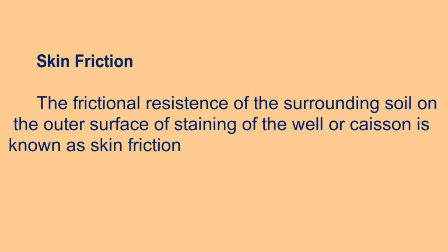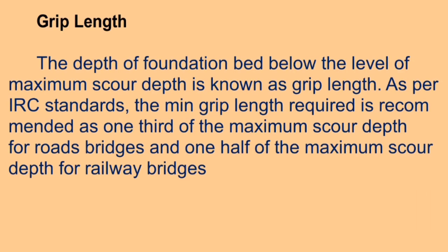Now, what is skin friction? The frictional resistance of the surrounding soil on the outer surface of the well or caisson is known as skin friction. What is grip length? The depth of foundation bed below the level of maximum scour depth is known as grip or grip length.